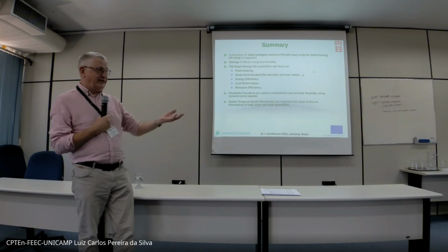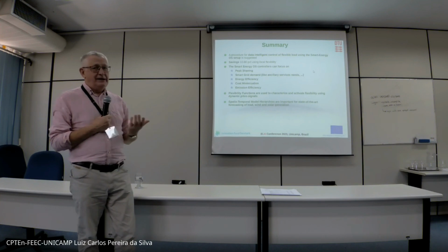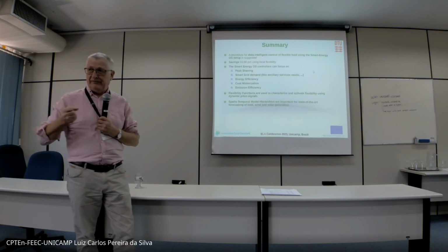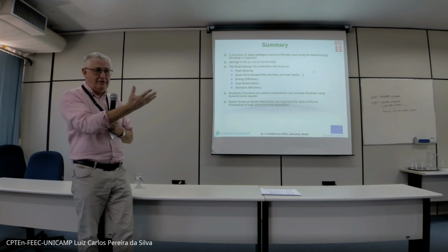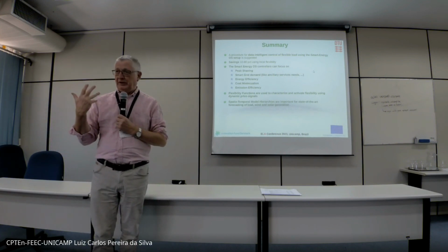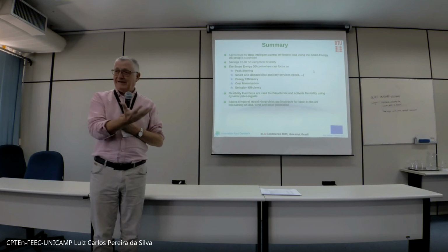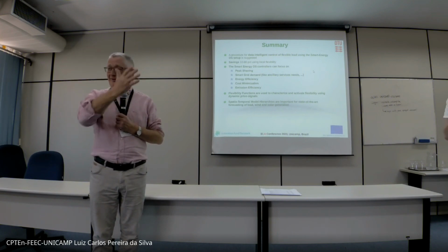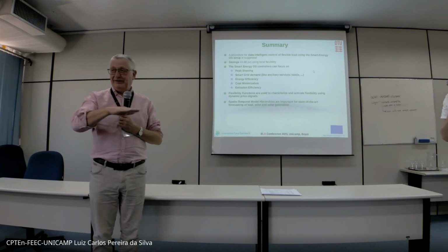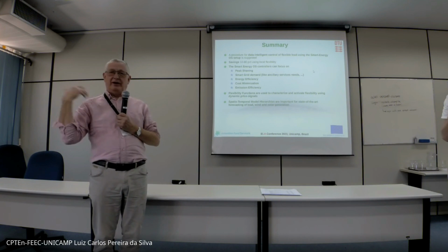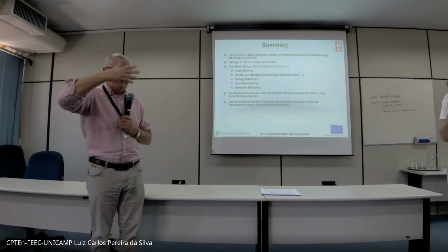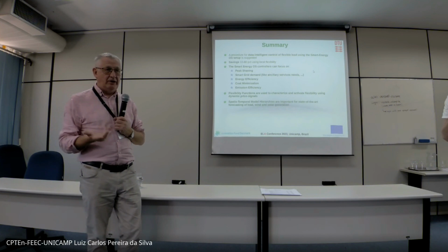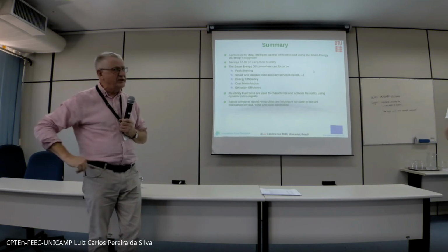Yeah, we save money basically in all cases. For what we did with the summer houses in Denmark, we have a lot of wind, and as I said, we are often turning off the wind turbines because we don't know how to use it. So one thing we did in this Flexible in the Denmark project is we used summer houses with swimming pools simply to store the excess heat. We simply overheat the swimming pool a bit, not so people are boiled, but up to maximum 32 degrees, and normally it's around 25 to 26 degrees. Due to the large thermal mass, if we raise the temperature by 3 or 4 degrees, we can turn off heating for the next couple of days or something like that. So that gives a lot of flexibility. It saves a lot, I think up to 30% or something for the summer house, as far as I recall.